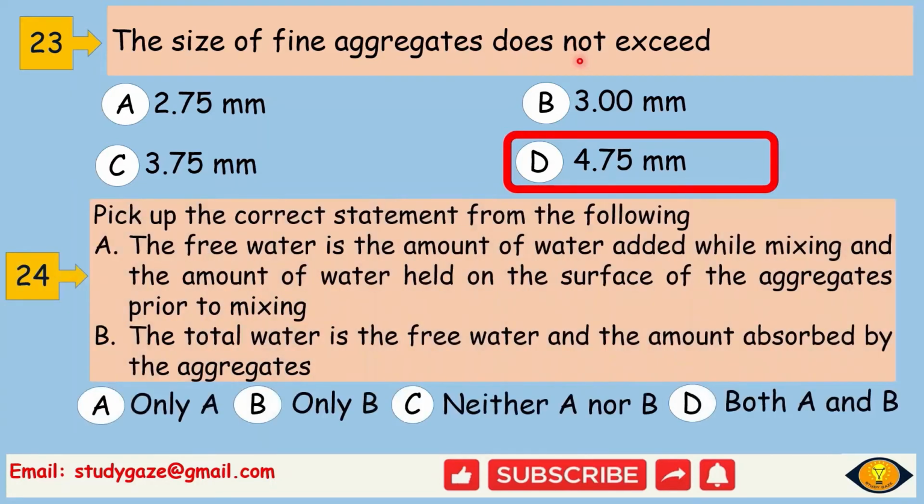Next, pick up the correct statement from the following. A. The free water is the amount of water added while mixing and the amount of water held on the surface of the aggregates prior to mixing. This option is also correct. Next, the total water is the free water and the amount absorbed by the aggregates. So this is also correct. So the correct option is D. Both A and B statements are correct.